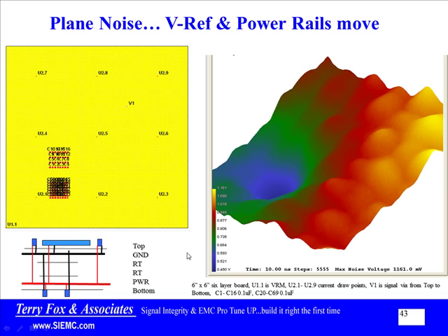But in this particular case, what I was looking at was the noise on the power plane when these things pulled current. Now, when they pulled current, you'll notice that in this area where I have a lot of capacitors, that's that blue area, it tended not to move very much. But in this particular case, it was moving almost half a volt.